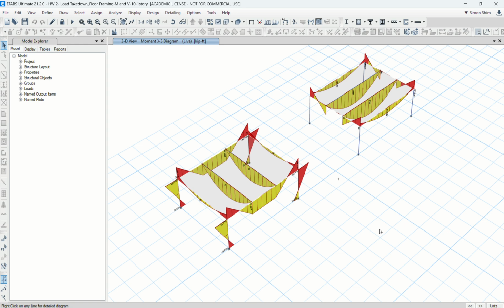So P times L, right? So the moment here is P times L. We draw the moment on the tension side because the beam deflects like this. Tension force is developed at the top side. So this is maybe one kind of negative. We usually call this that.